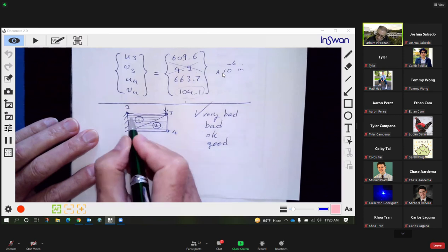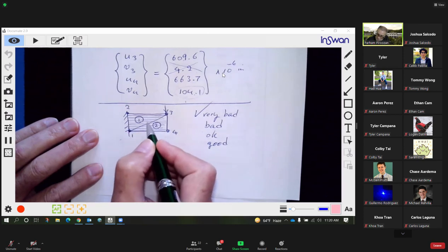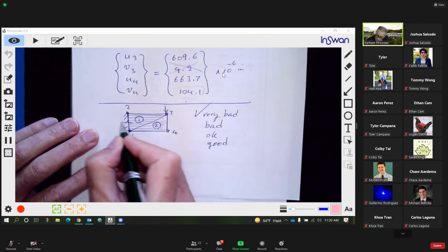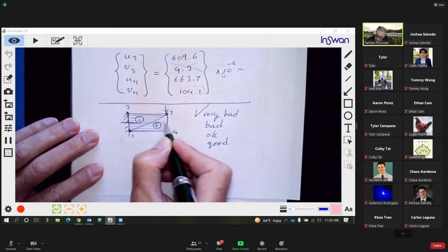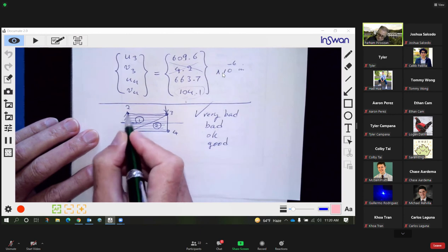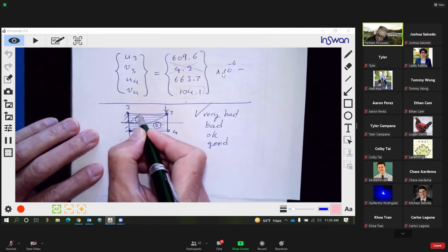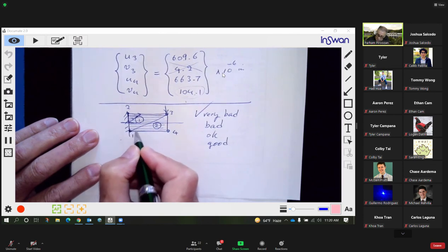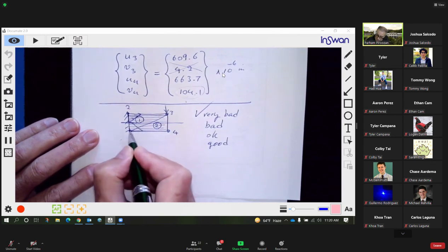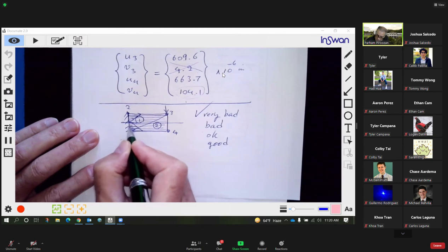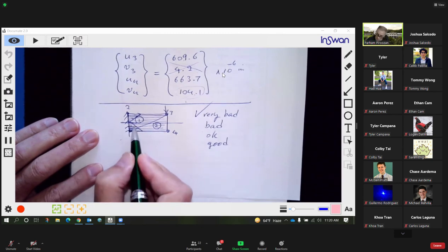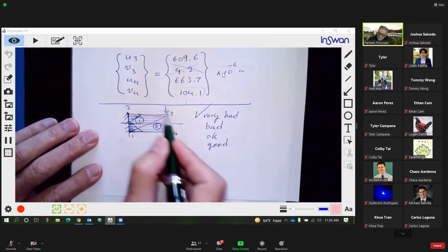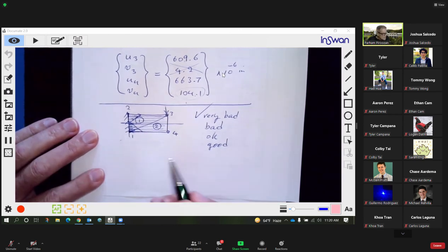When we apply this, these stresses are positive, and they are varying linearly up to this neutral axis, neutral plane, and then these stresses vary linearly like this. So this sigma x should actually vary like this. And these stresses are actually compressive, they are negative here. So just one stress sigma x, it is very bad.